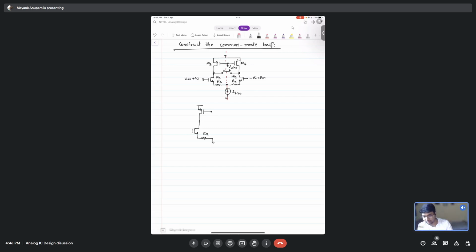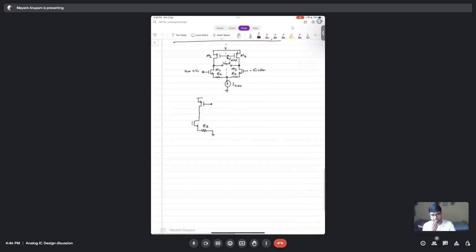So what happens to the bias current? I mean, what happens to the bias sources in the small signal picture? In small signal analysis we don't do it, sir. For DC analysis we considered, and we will use two different approaches, sir. Correct, true. So what happens in the small signal picture to any current source? Current source will short circuit, or voltage source will, sorry, open circuit, sir. I think current should be open circuited, isn't it? Yeah, open circuit.